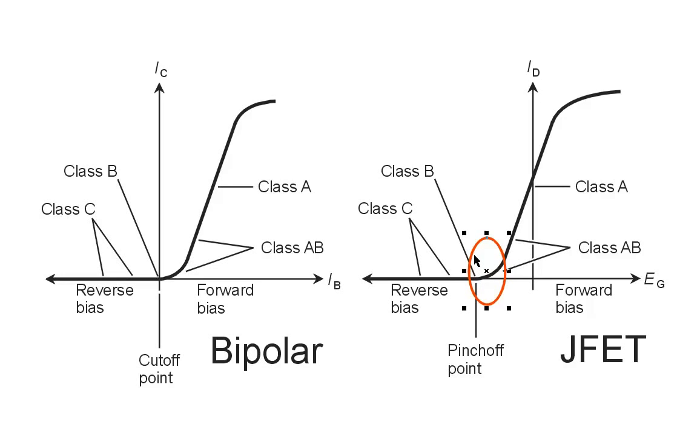One of the interesting things about all of this is that in order to get significant amplification with these Class AB amplifiers as opposed to Class A, we need to drive them harder. I've represented that by making the ellipse here, as it were, bigger and bigger.